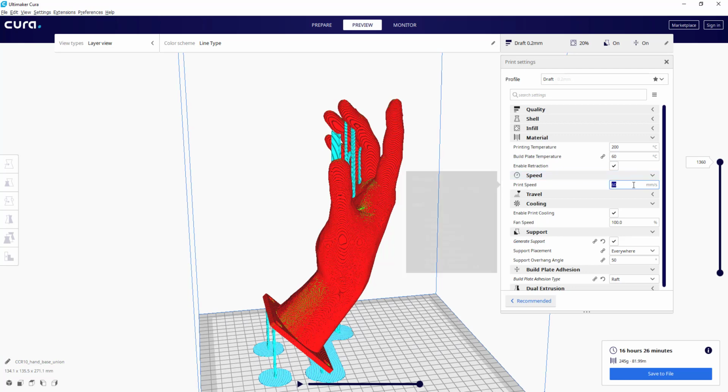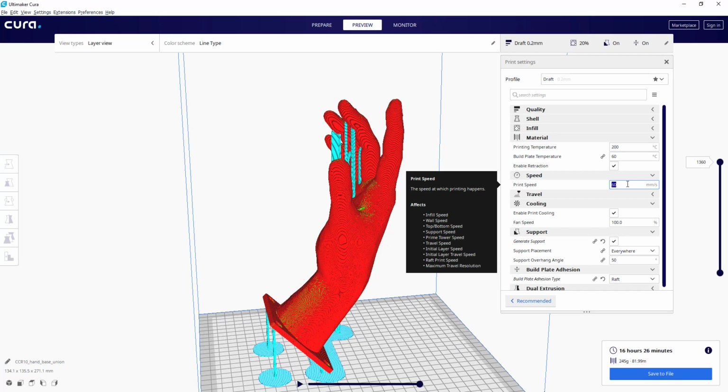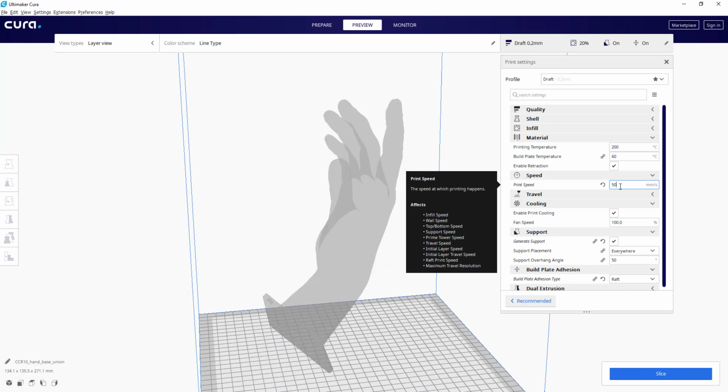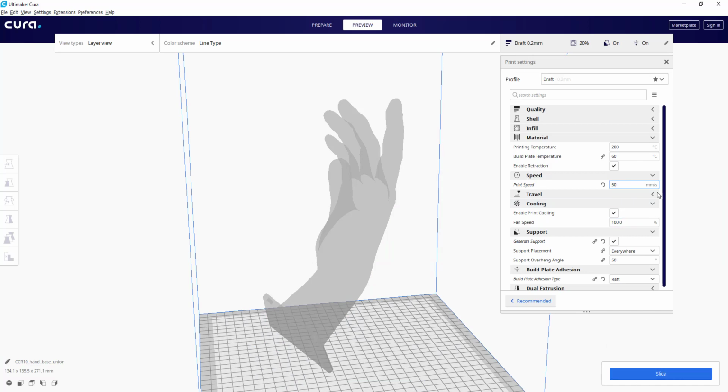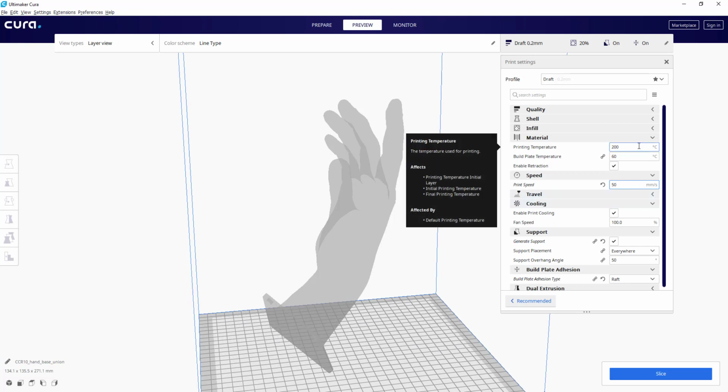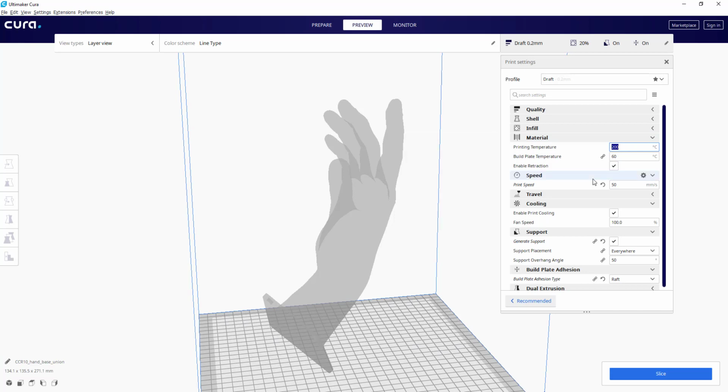We can also change the speed of the printing process. It is not our advice to use a 60 millimeters per second speed, 50 millimeters per second maximum. The best for most non-professional machines is from 40 to 55 millimeters per second. CR10 works really well with a speed of 50 millimeters per second. If we change this option and slice it again, the time will be greater as it lasts longer to do the layers.